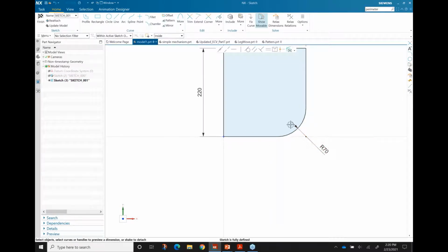So sometimes we have a dimension and it used to be a circle, so it'll show it as a diameter. We've all had that, right? And it just doesn't look right. Or it could be that it shows a radius when it should be a diameter. Well, all we have to do is right-click on our dimension, convert to radius. Right-click, convert to diameter, and you get the idea.